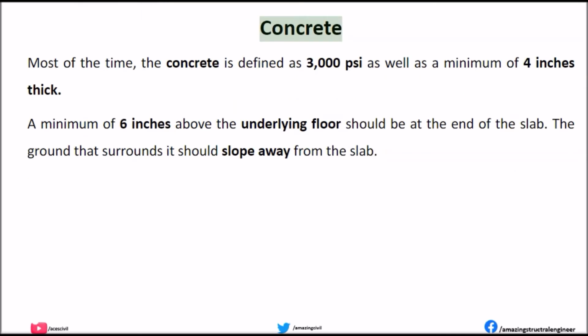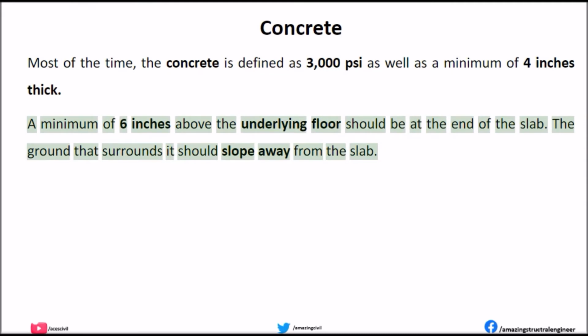Concrete. Most of the time, the concrete is specified as 3000 psi and a minimum of 4 inches thick. The edge of the slab should be a minimum of 6 inches above the underlying ground. The ground that surrounds it should slope away from the slab.